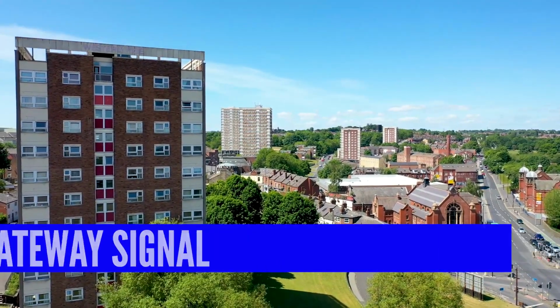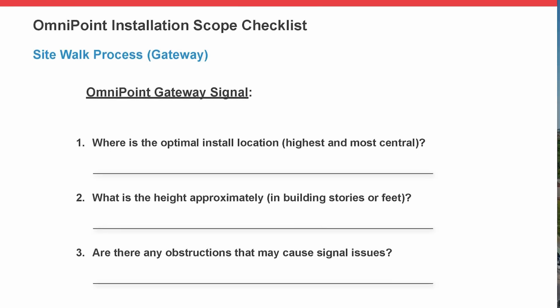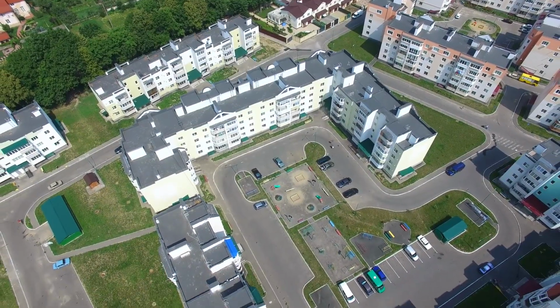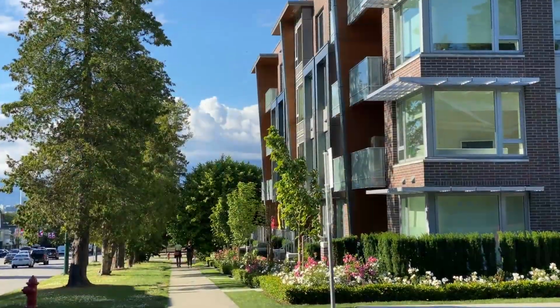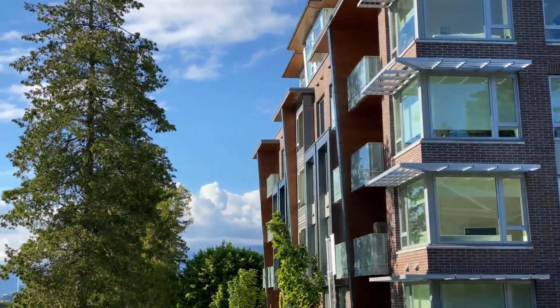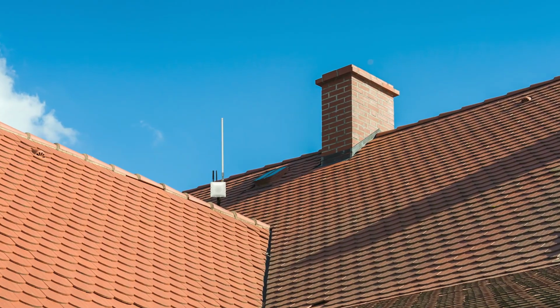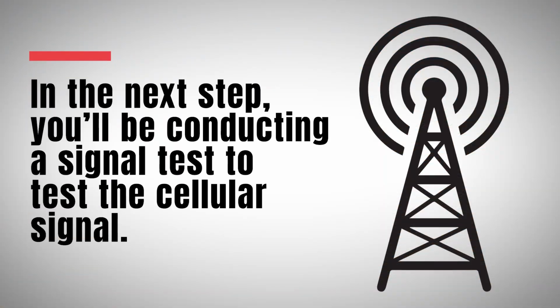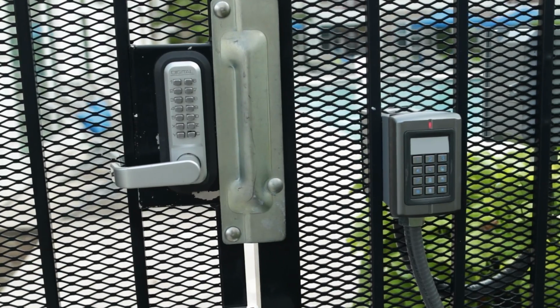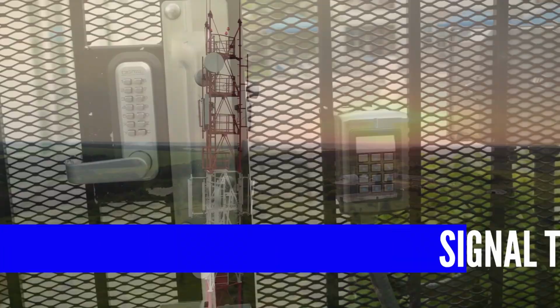Gateway signal. Identify the optimal installation location. Look for the highest and most central point. Estimate the height in either building stories or feet. Check for any obstructions that might interfere with the signal. Determine if additional gateways will be needed and note how many. In the next step, you'll be conducting a signal test to test the cellular signal. Please ensure all doors are closed prior to conducting this test.